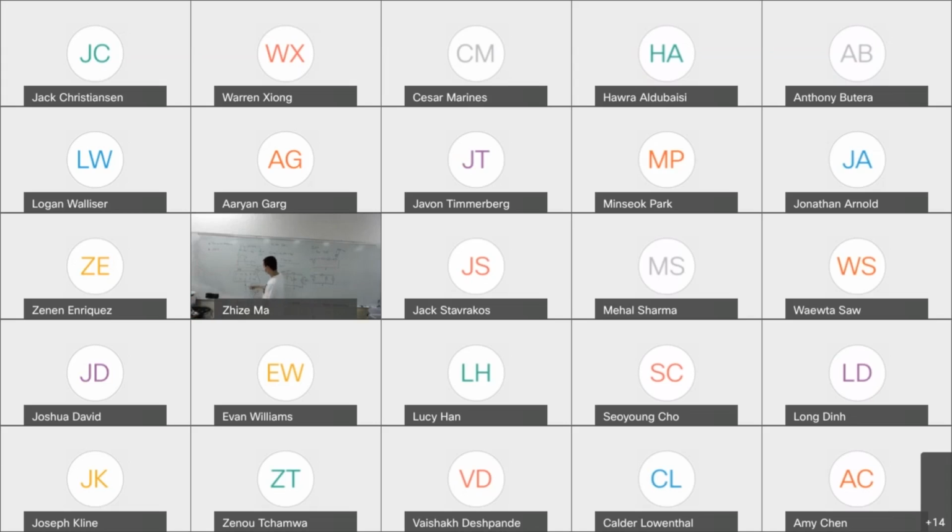And remember, on the left part of your AD2, there's the 1 plus, 1 minus, 2 plus, 2 minus. That's called the scope. These two pins can measure AC signal and DC signal. For DC, it can work as a voltmeter. So I assume you will use pin 1 as the voltmeter.